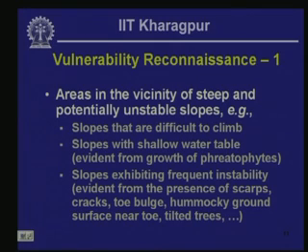Then thirdly, slopes exhibiting frequent instability, which is evident from the presence of scarps, cracks, toe bulge, and undulating or hummocky ground surface near the toe, tilted trees, tilted electric poles, and so on and so forth.